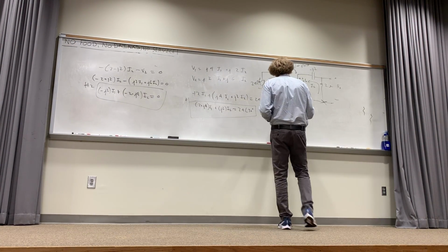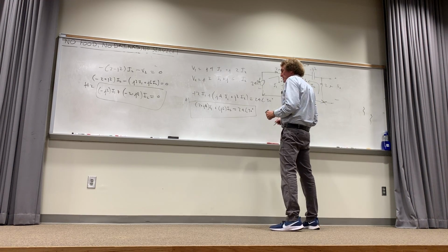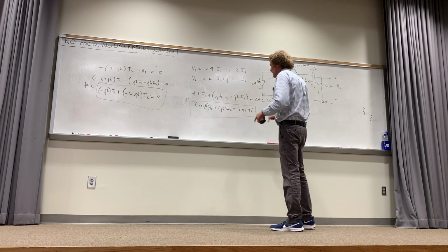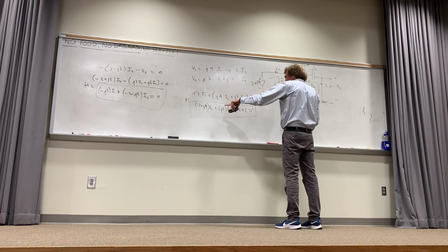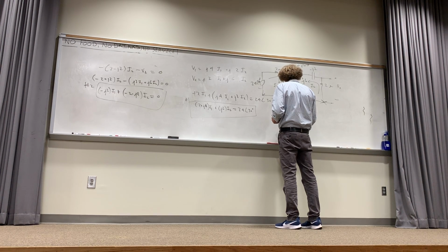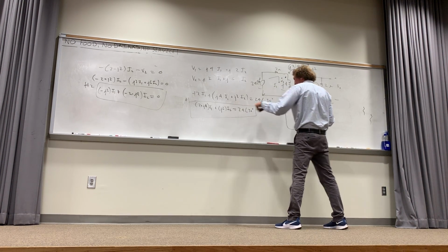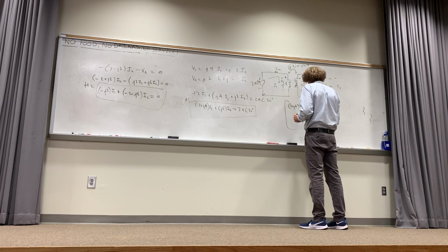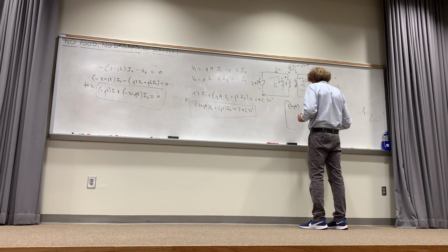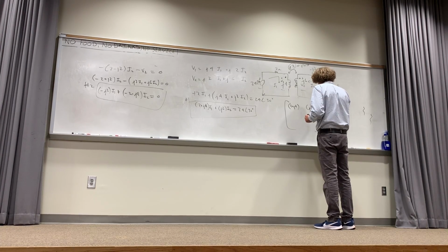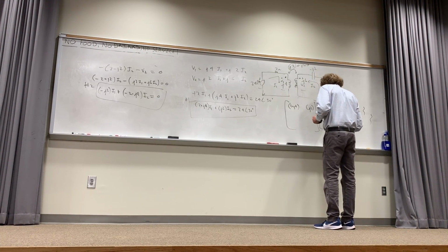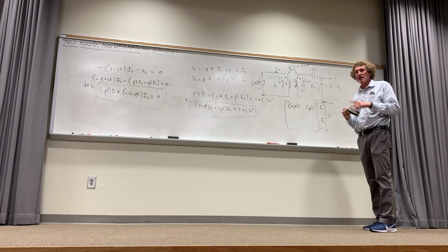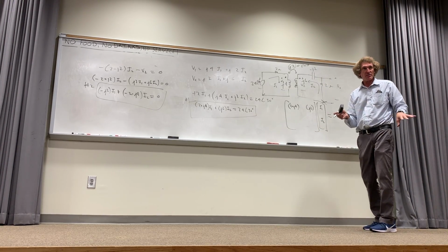So what matrix equation am I going to solve? Well, it's this one. There's my first equation. My first coefficient is going to be 2 plus J4, right? Now my second equation, the second coefficient is J2. It's times a column vector, I1, I2. I know MEs and aerospace engineers are used to this. The IEs, I'm not sure if you're used to this or not, to be frank about it.